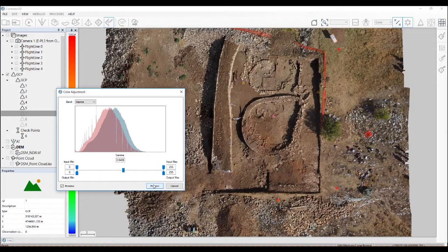So once you process and you apply your resulting change, be careful, because it will permanently update the mosaic. So maybe you want to make a backup before doing this. And also another thing I want to mention is that you can also play on the different bands. So if there's a band offset, you see maybe there's too much red in your image or too much green value, then you might want to go and adjust that band individually to adjust the color of that band.